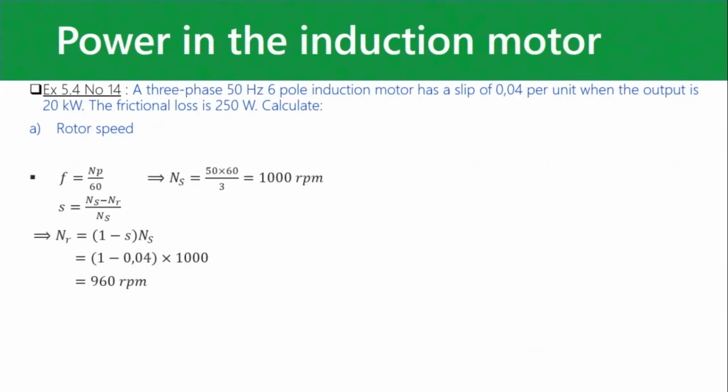So this one, we just work out the rotor speed quickly. Nothing much there, but just with what they give us, if they ask you anything like frequency, speed, this should be NS, synchronous speed, pole pairs, and you use that stuff always to get this NS. Now, once you have that, in this case we have to work out the rotor speed, the actual machine's rotational speed.